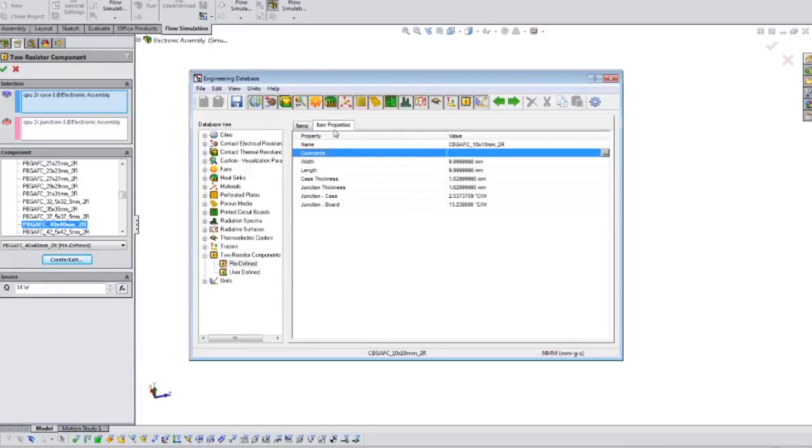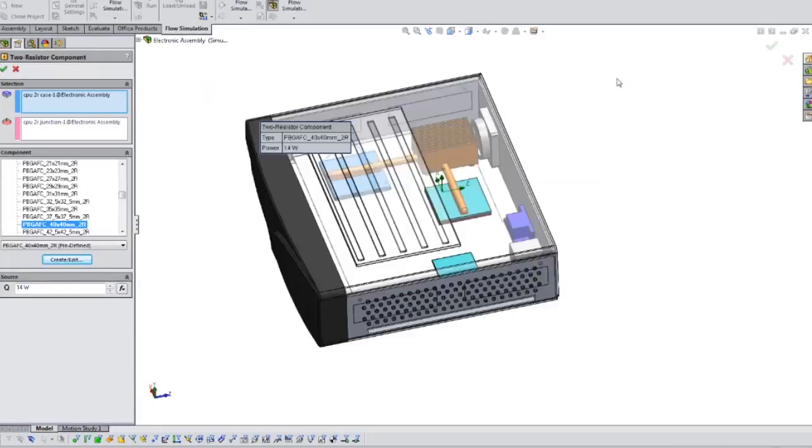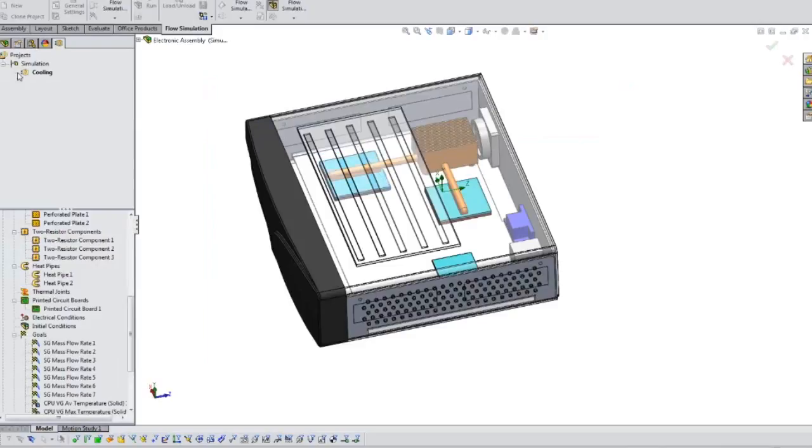So once we pre-process the model, we also do things like simplify it. No PCB has just these 3 components on it. There's often a lot more other components. If those components aren't blocking airflow or generating heat, we probably don't need them inside of our SolidWorks Flow Simulation. So we usually eliminate those and suppress those. We do that easily using SolidWorks configurations inside SolidWorks.